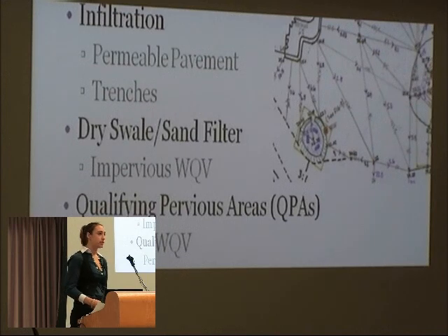Runoff was interconnected with the grading process. We used 3 best management practices to treat the water quality volume of the first inch of runoff as specified by the Rhode Island Stormwater Design and Installation Manual, Standards Manual.